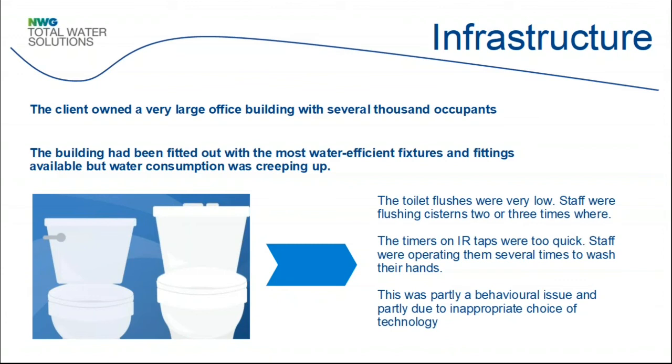And this was also another client who had set benchmarks for water consumption, which were actually probably a bit unrealistic. One of the things that came out of the audit was when you look at your long-term data, you average about 38 litres per person per day, which is actually very good for an office. And their target was a lot lower than that. But what the data demonstrated was it was actually going to be very difficult to achieve the aspirational target that the client wanted.